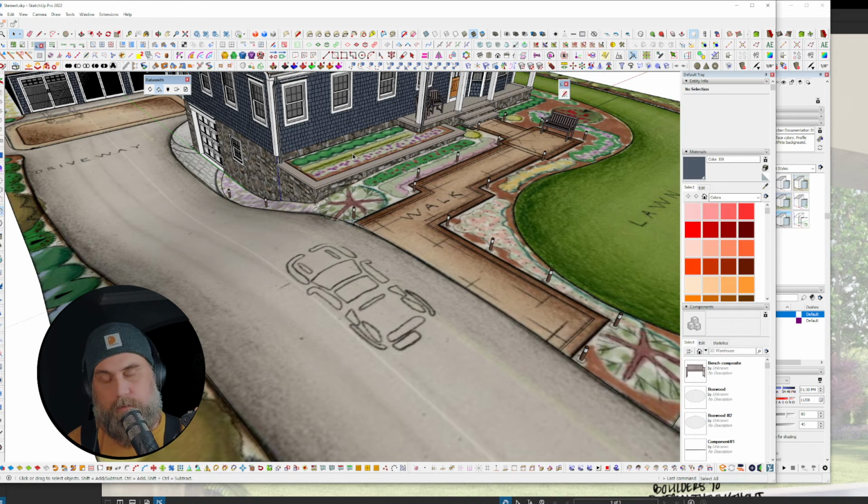And if you understand all of that, then this becomes a really powerful way that you can design in 2D, take your 2D plant symbols, bring them into your 3D model, drop them down onto your terrain, your 3D surfaces, move a copy over into another instance of SketchUp, use your Direct Link plugin, access both of them at the same time, and be able to go through systematically and replace those plant symbols with 3D plants that you've either imported or used through the Twinmotion available libraries.